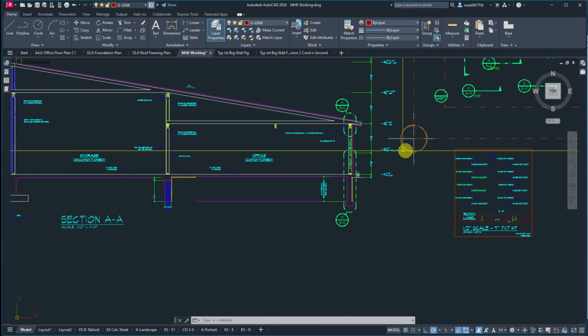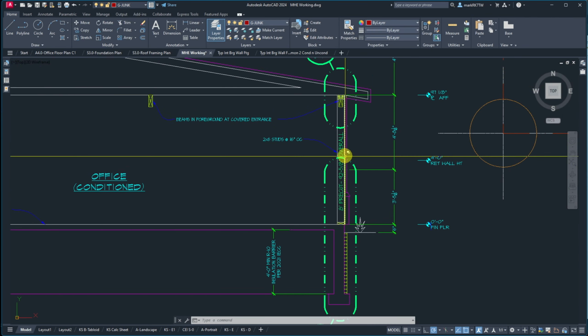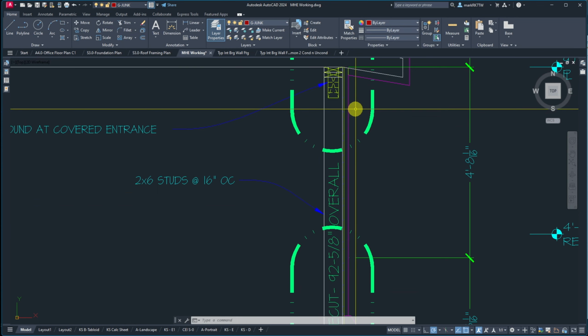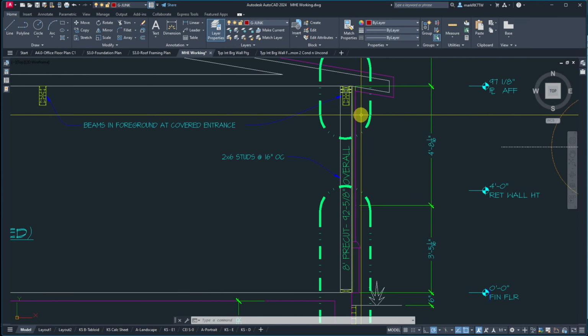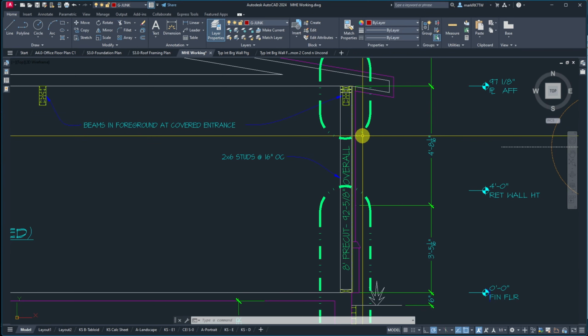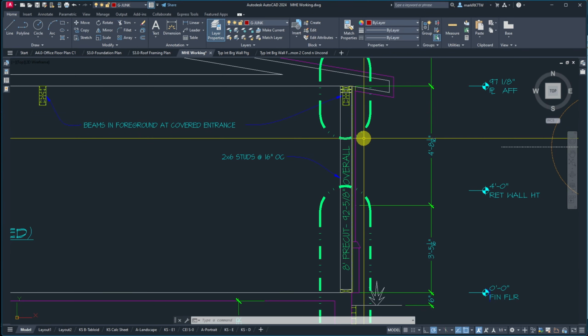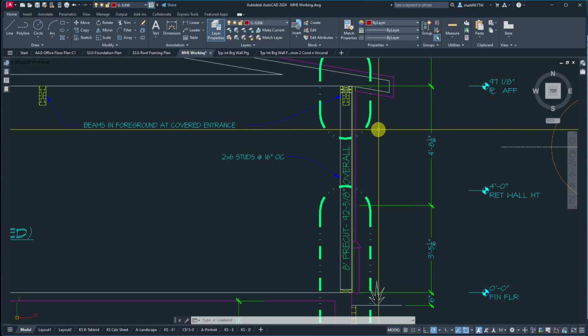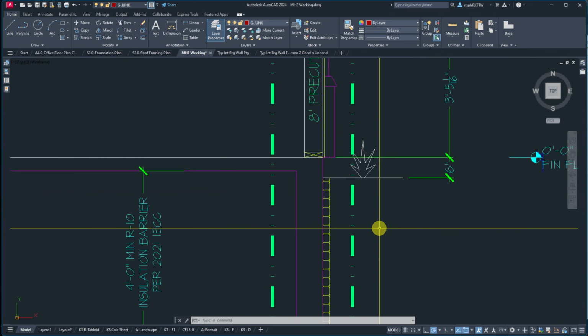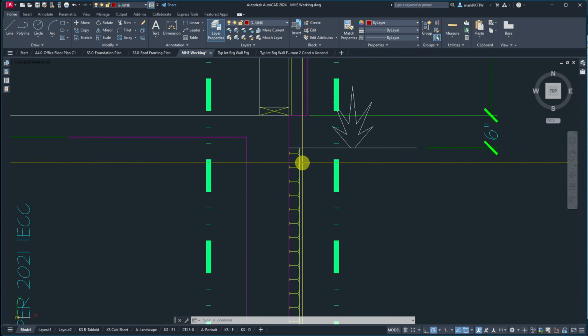This is a heated office space. I've got a cavity insulation. Because I'm in Montana, we have a Montana DEQ regulation that allows us to still use R21, even in 2021 codes. It's ridiculous. We are in climate zone 6. Why we're allowed to reduce is beyond me, but we are. So the owner would like to take advantage of that.